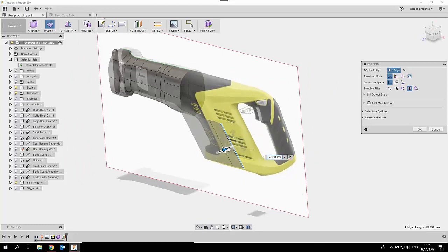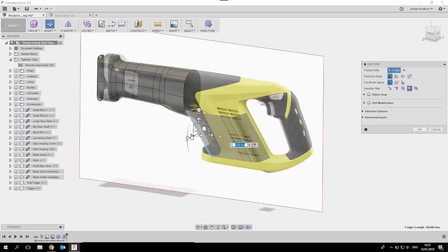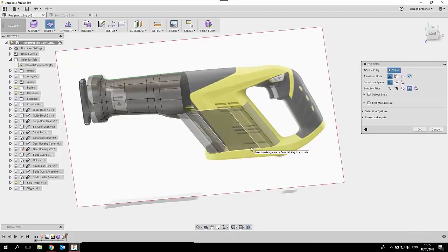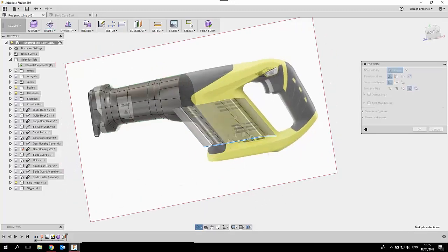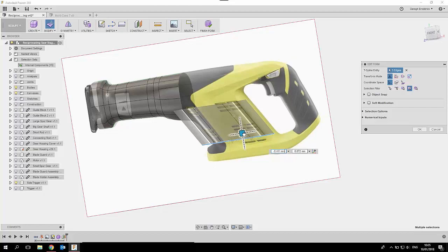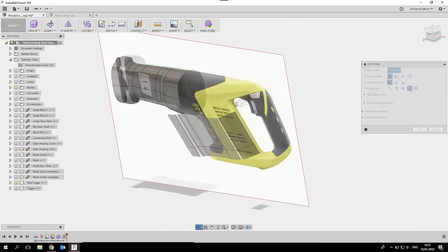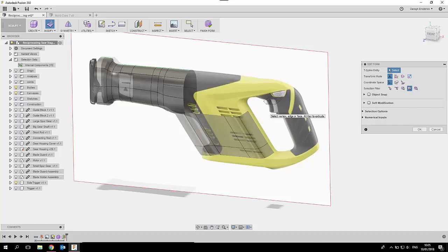And likewise I can just do that again, and we can just drag that in. Then using the same tool again, just drag this out, and same here. And we've created a number of faces in a matter of seconds. So typically in other CAD packages you'd be dealing with 3D sketches, construction planes, and so on and so forth, and then dealing with lofts, sweeps, different kind of features to try build a body like this.